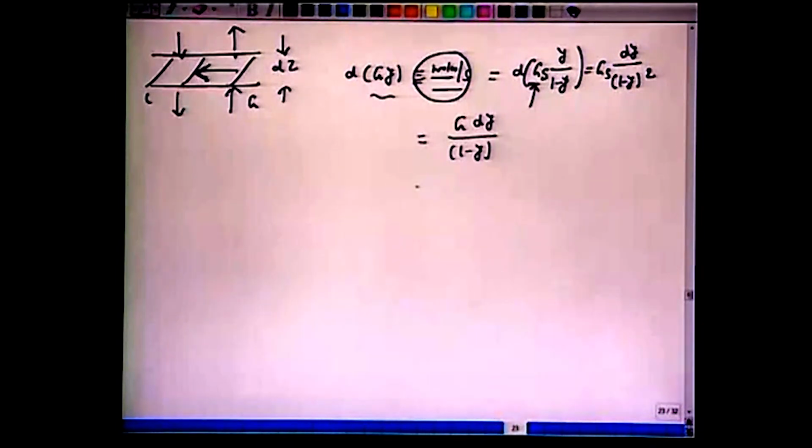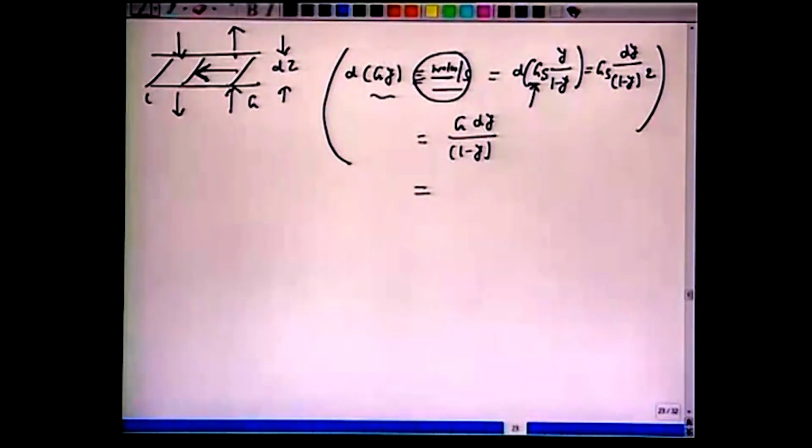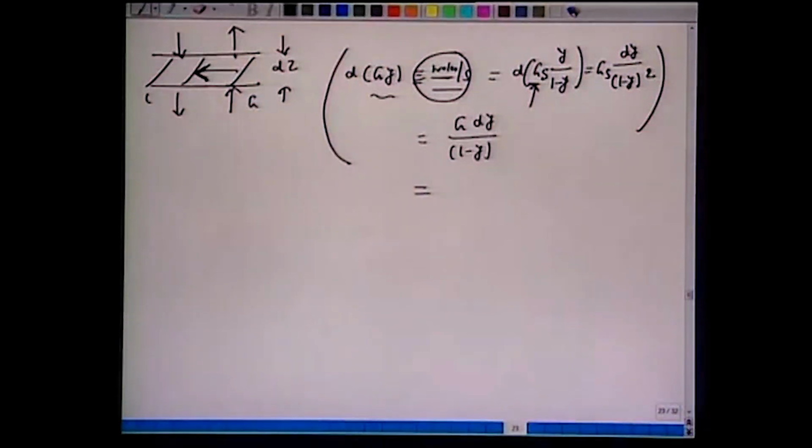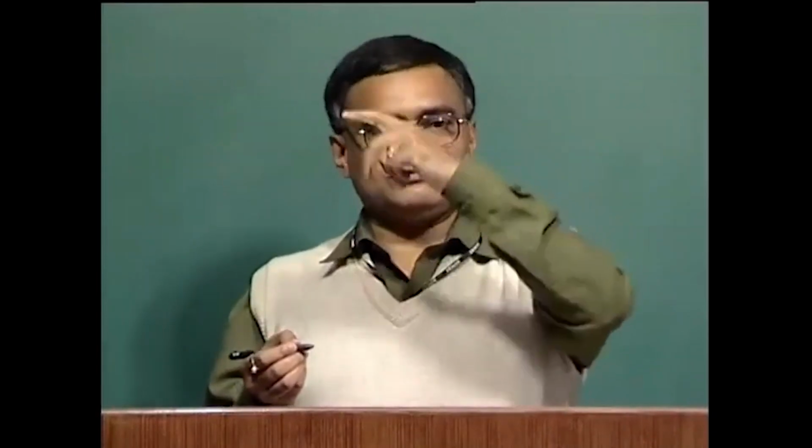But remember, the entire quantity which we have calculated and written in different forms can also be written in terms of the liquid phase. Whatever happens in the gas phase in 1 second, if 5 moles change across this dz, the same 5 moles will appear in your liquid phase. That is a species balance. Under steady state, there is no accumulation. So, if the gas flow rate is 5 here and 2 here, what has happened to 5 to 2? 3 must have gone into the liquid phase.